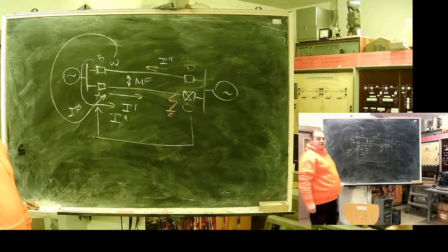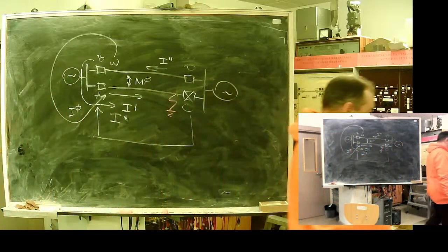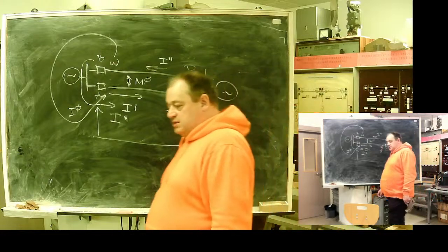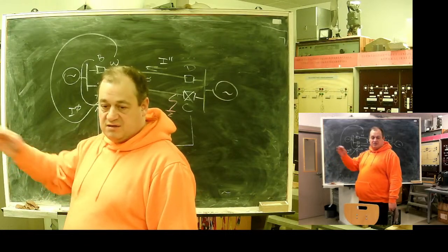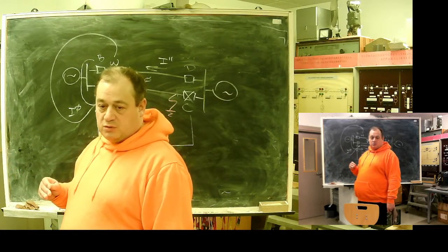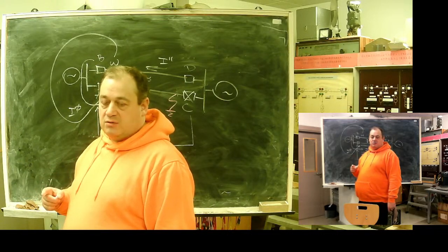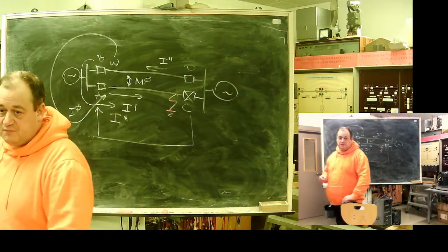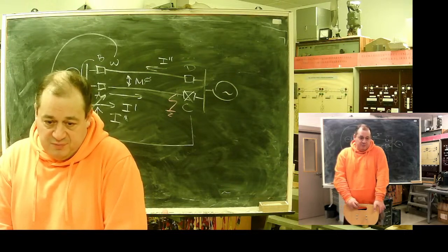Modern terminals have so-called compensation channel for parallel line. High-end relays allow to take zero sequence current of parallel line and compensate this shift of resistance due to mutual inductance. If you activate this channel, be very careful with sign, with polarity. You can make things much worse.